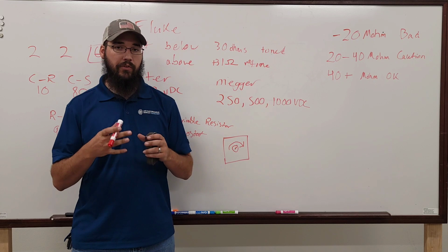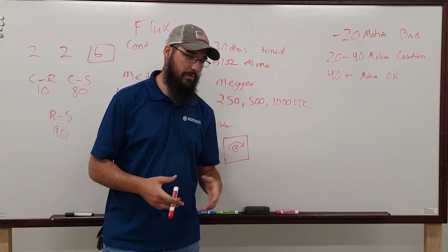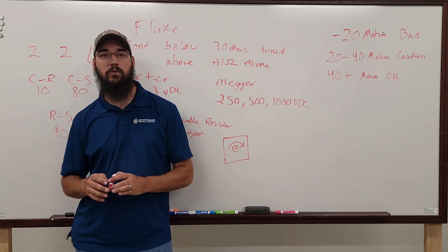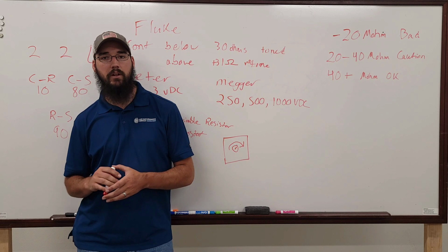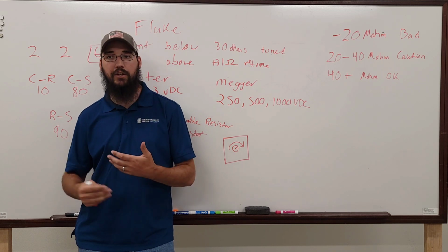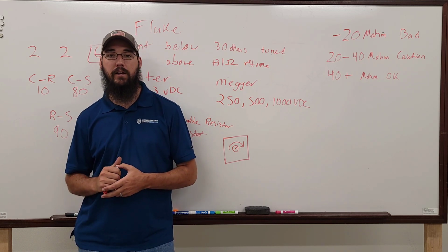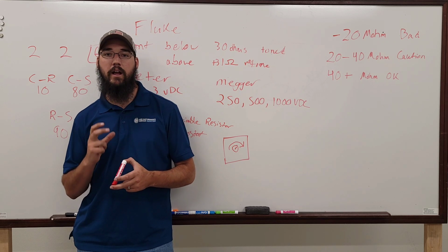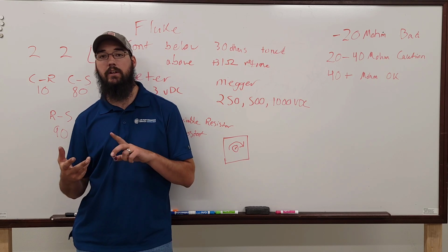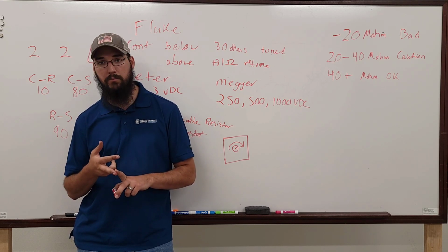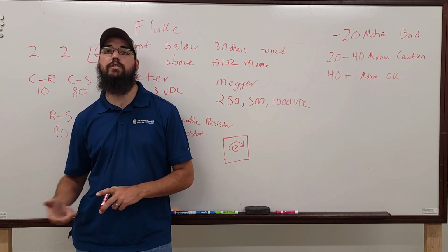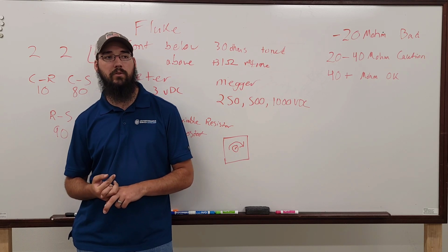Vibrations and alignments. One of the things, and instead of diving into the physical numbers of the readings and stuff, I don't think we need that as much. We have to be careful with how we use those numbers, because many times I've seen a lot of stuff condemned and it not actually be a bearing issue, right? If your bearing readings, your inner and outer bearing, are actually reading in okay range, but it's the horizontal, axial, and vertical that are the problems, don't write that motor up as bad bearings, because it's not. There's external conditions as to why those readings are that much.